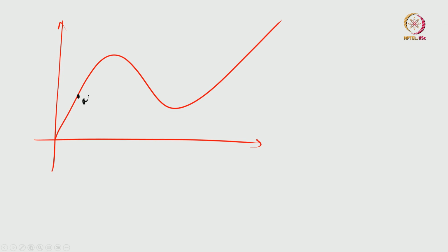If you bias the point such that you have a load line going like that, the load line being the line in an IV characteristic where you are biasing the device with the resistance that you are putting in, the device will oscillate around this point. But this point is a regular IV, the current is increasing with respect to voltage, so you are not going to get any microwave oscillation. We call it a monostable bias point, because you are not explicitly getting anything out on microwave here. Now, this point is suppose B, and this point is suppose C.